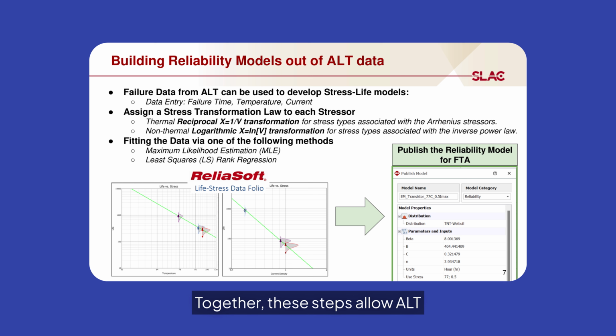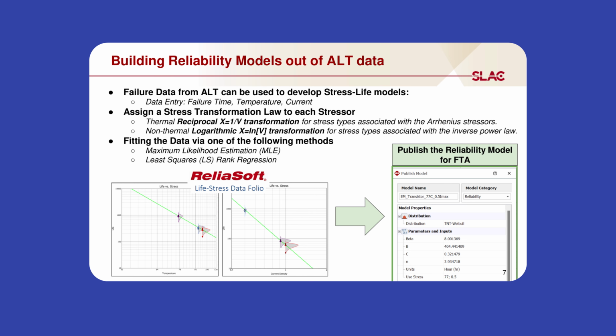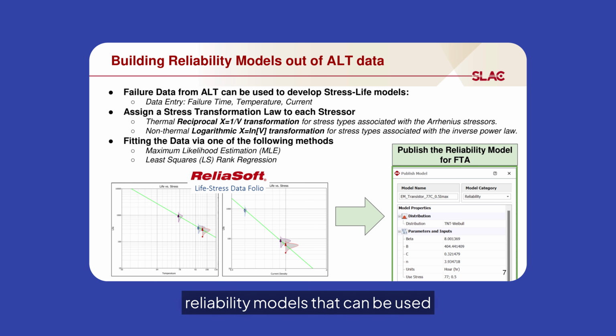Together, these steps allow ALT data to be translated into predictive reliability models that can be applied across a range of operating conditions. As shown in the pictures, we use ReliaSoft software to convert stress-life data into reliability models that can be used in our fault tree analysis.